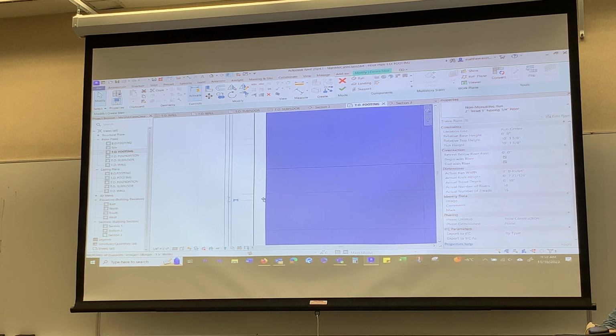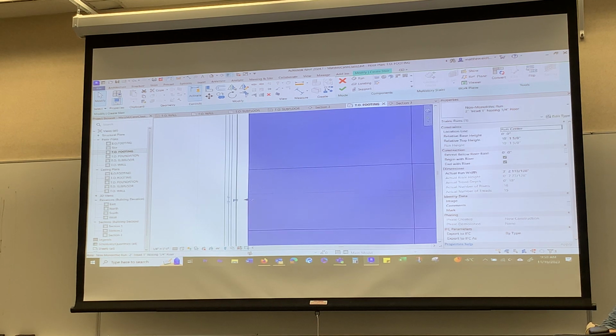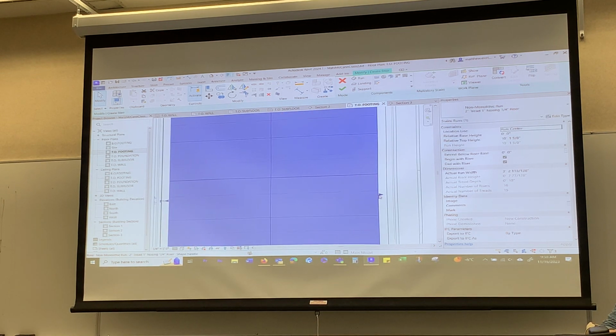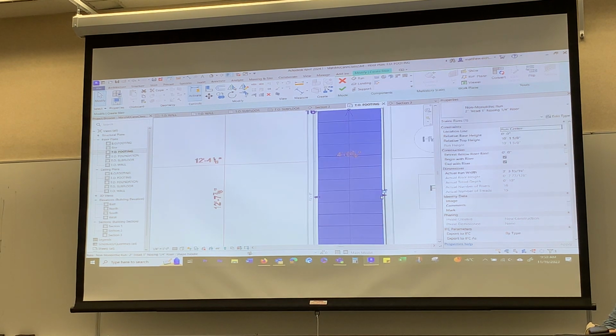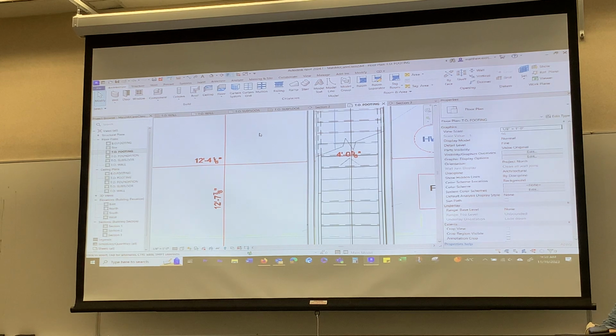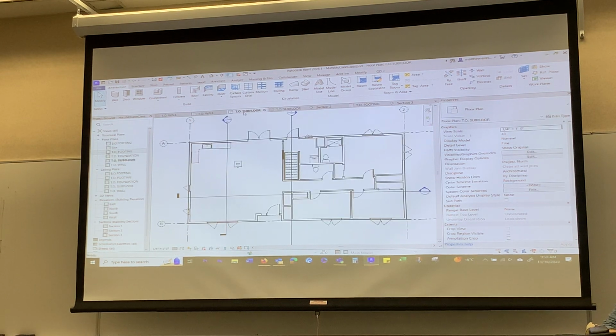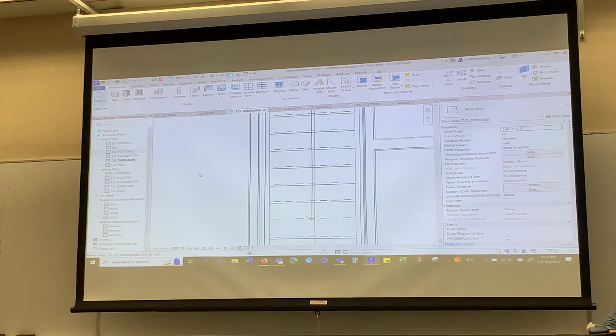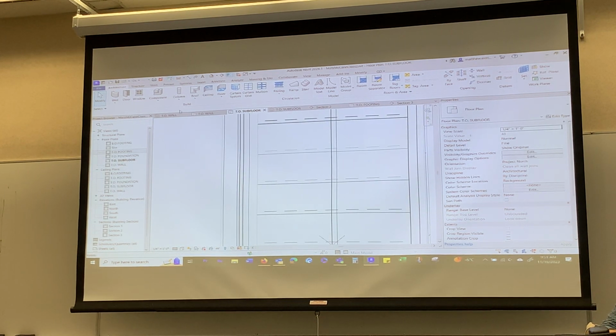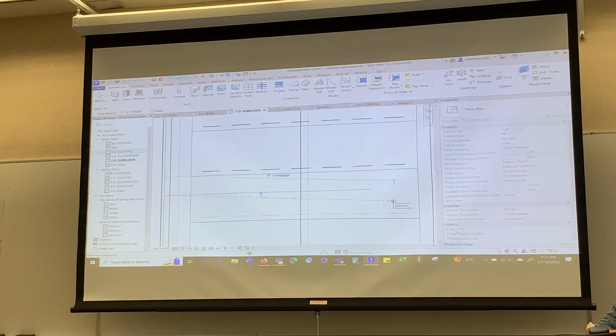And it's hard to see what you're doing. Go like that, and about like that. So it's 4 foot and 5/8 is what it's telling me. So I'm just gonna click to finish. I can go back and edit them later if I don't like it. I could have done this beforehand, but I'm gonna go to top of subfloor and find out what space is actually there from drywall to drywall.